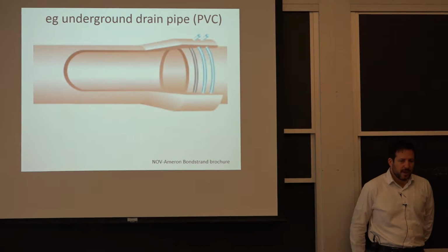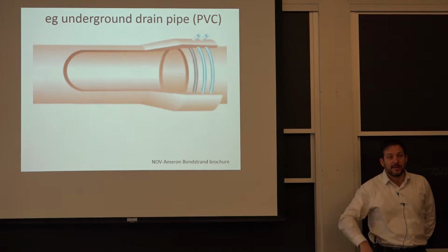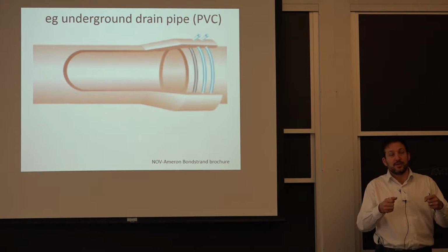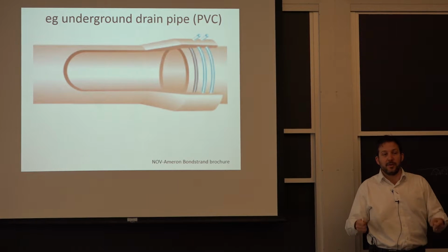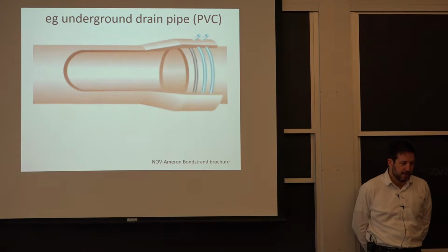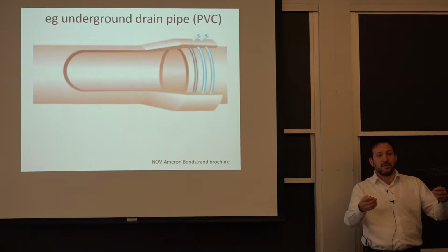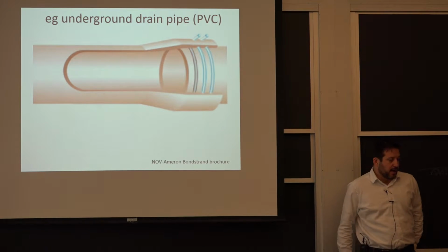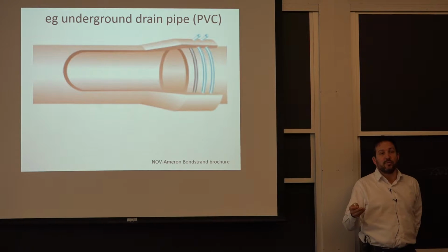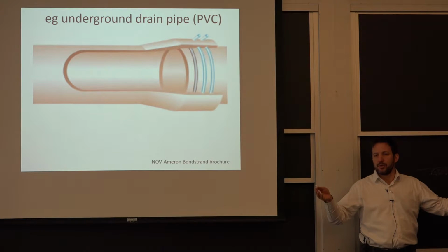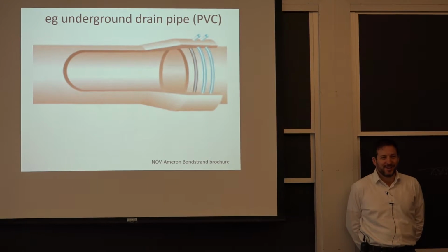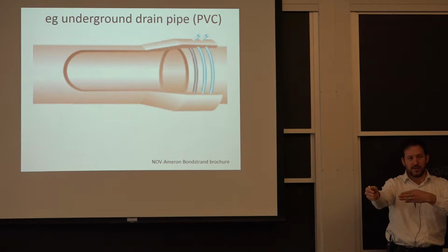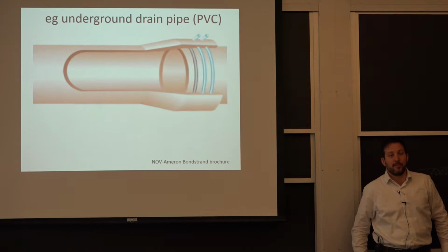Let's say you have a large drain system that's 100 feet and you try to make it straight. They will do that out of stainless steel, for example, because first of all, if there's a problem, the stainless is just going to deform a little bit. It won't crack. It's very, very tough, just like structural steel. But with plastic, you can start having some cracks, even from a one-time movement, because of the way the joints are made, if you have solvent cement. And mostly also because now you're talking about inches of movement over that 100 feet of length. So instead of being 3/4 inch, it could be as much as 3 inches. And 3 inches, if you have a lateral, means a lot of movement. So if you're going this way and then the end has to contract 1.5 inches, it's making a lot of bending moment on that connection.